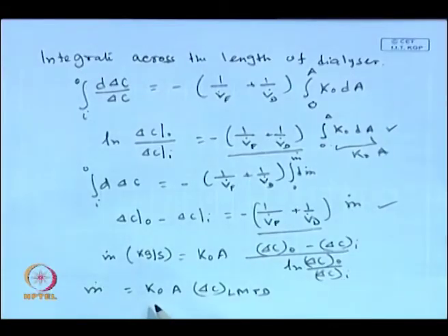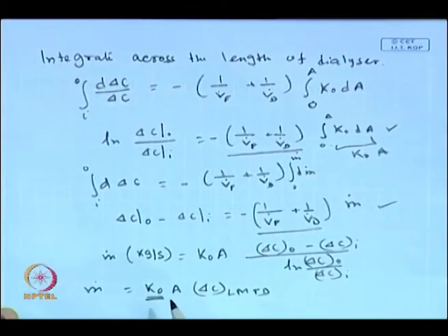Knowing these values, knowing the operating condition, that means flow rate, using the flow rate you can find out the mass transfer coefficient in the feed side. You will be in a position to calculate the mass transfer coefficient in the dialysate side. If you know the thickness of the membrane and the diffusivity of the solute through the membrane, DIM, then you can estimate the resistance in the porous membrane as well. Now, using these 3 values you will be able to calculate the overall mass transfer coefficient.